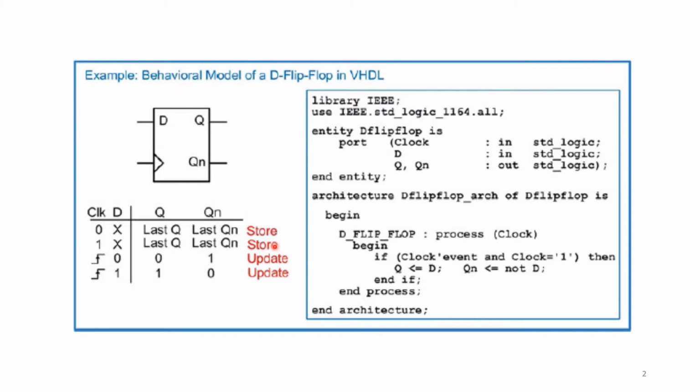So whenever we are writing the VHDL code, first we check for the asynchronous action, if there is an asynchronous action. Here there is no asynchronous action. Asynchronous means if you have reset or preset, something like that, then we need to check for that one. Like here, after begin, we check if reset is 0, then do something. Later on, we check for the synchronous action. Synchronous means with clock. So with clock it is transferring the values. If clock is active, then transferring the values, D to Q or something like that. So remember that. It will be needed for the other examples as well.